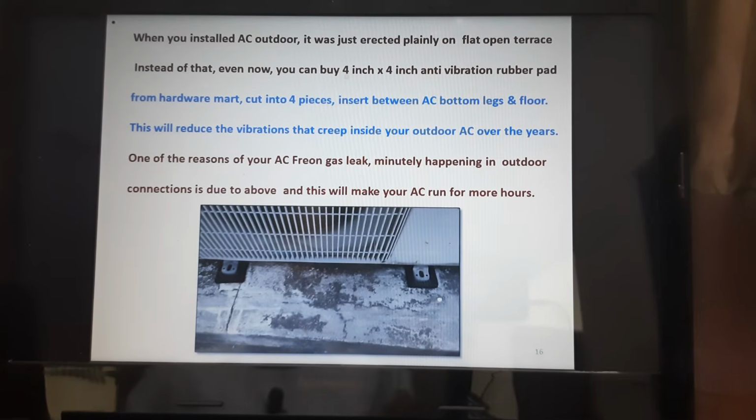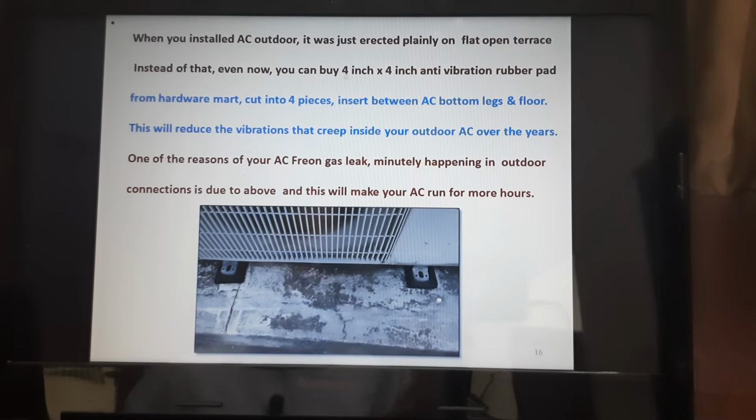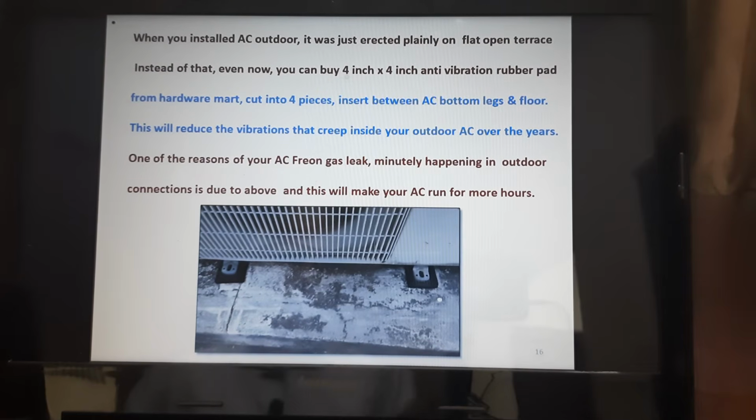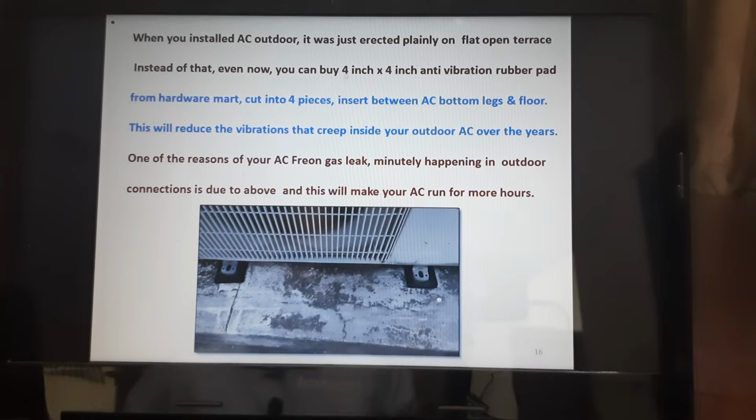Coming to the AC outdoor, why are our AC outdoors having a slight leak of this freon gas? Right from day one when we are installing, or even if we have installed a decade-old AC, you can still use the black rubber pads, anti-vibration rubber pads. It's just 1 inch by 1 inch. You can install it at the bottom or the foot of the AC, so that the AC need not vibrate, or the vibration need not affect the AC performance, and the leakage need not be caused because of vibration